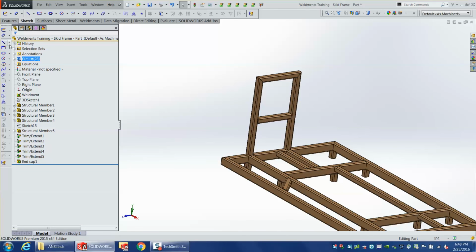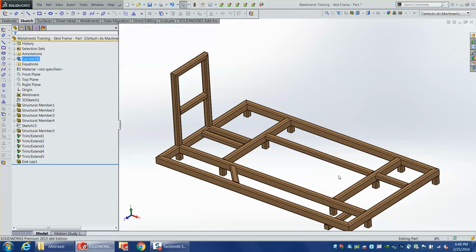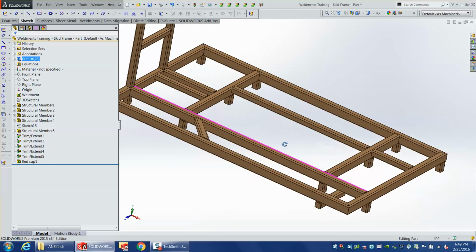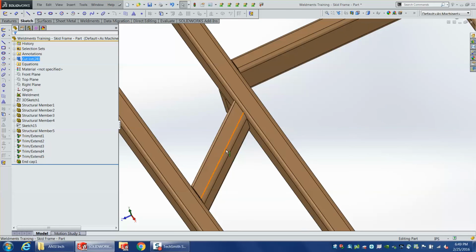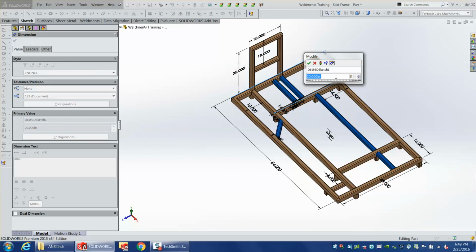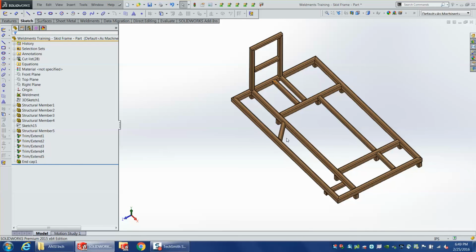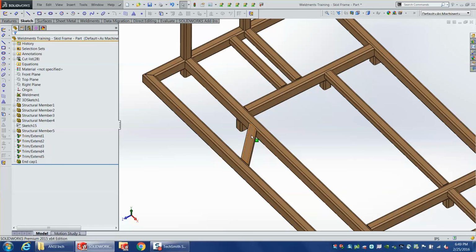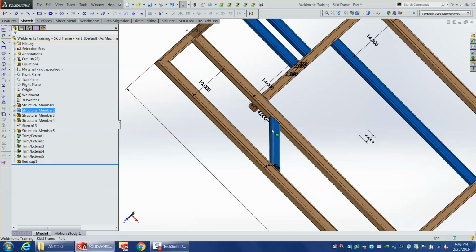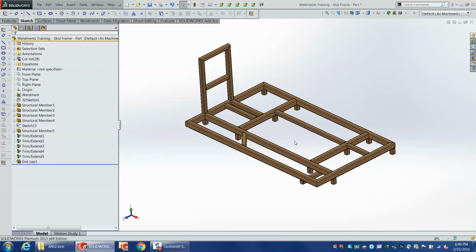I haven't had this one. This one is quick. You can make changes to things and use it all over the place. Yeah, it's very nice for the automatic trimming features too, and setting up the corner treatments. If I had this cut set up, and then let's see, if I change this dimension here, actually 3-4 components all change their lengths, which you might not have even realized. This one relocates, those two get longer, this one gets shorter, so that's the main power of it there.